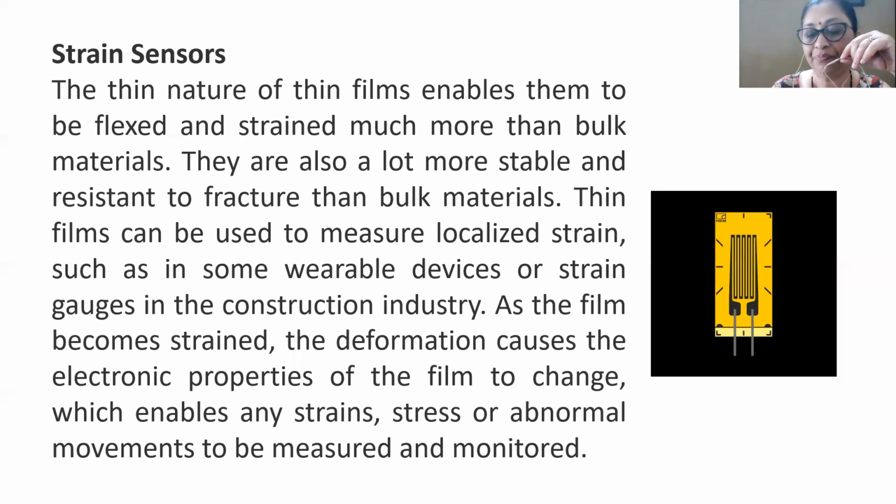So this is what is about the strain sensors, and such type of strain sensors are used in weighing machines. Electronic weighing machines, all of you know, and you are using it, and in such weighing machines the strain sensors are used. The material which is used for strain sensors is either metallic or semiconductor. Semiconductor strain sensors are more sensitive as compared to metallic strain sensors, because the change in the resistance which is produced in semiconducting material is of greater extent.